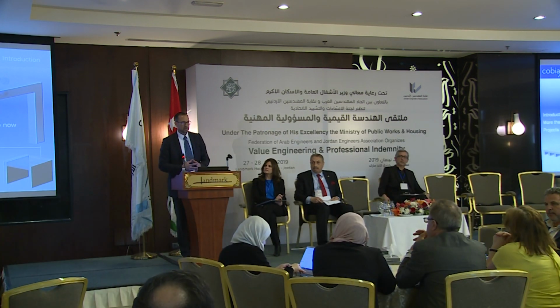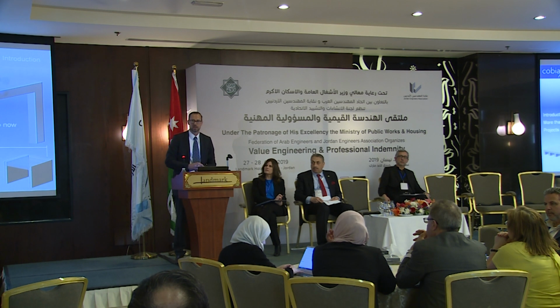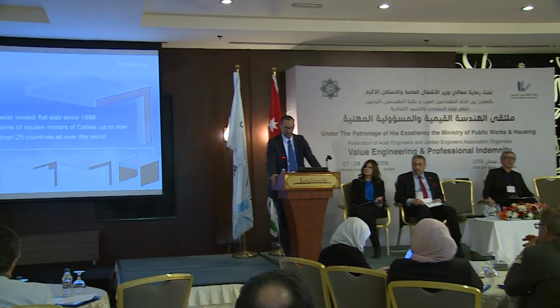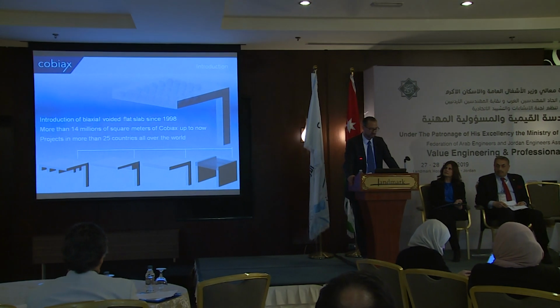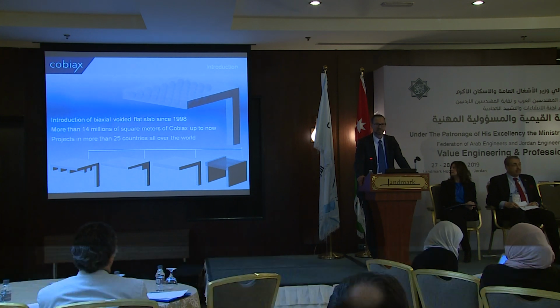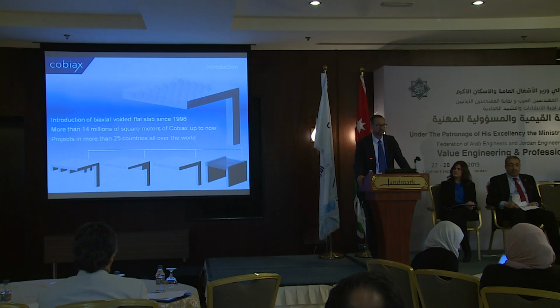What did we do in the past? We tried to bring together different advantages of well-known and established slab systems, as you can see in this slide. First of all, you see the waffle slab, then rib slabs, which are somehow the same. Then you can see a slab with capitals, then the flat slab, and the last example is a slab with pipes inside to reduce some weight.